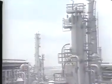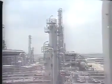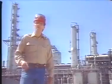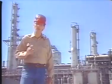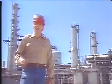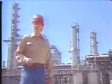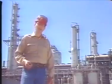Although there are many different types of distillation columns in any refinery or chemical plant, the goal of each is the same: to produce quality products that meet specifications at the lowest possible cost. Setting specifications for products allows us to control the type or range of molecules that are included in any one product. To determine product purity, we use boiling point tests or actually measure the percent of heavy and light key components in the product. Other specifications are set for flash point, API gravity or specific gravity, and color.